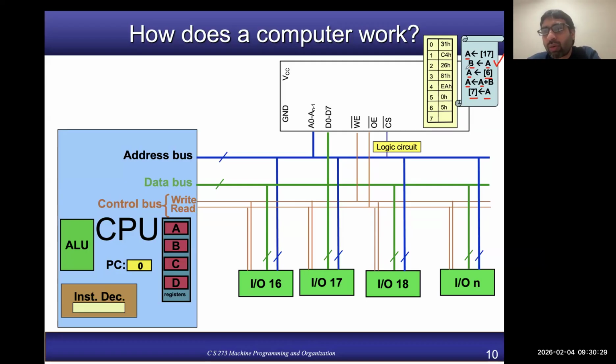But the important point is that all the instructions, even when you write them in assembly, are basically converted into bits, 1s and 0s, a binary code. But for our ease of understanding, we don't represent that code in binary form, but in hexadecimal form, by combining every 4 bits of the code and representing them as a hex character.